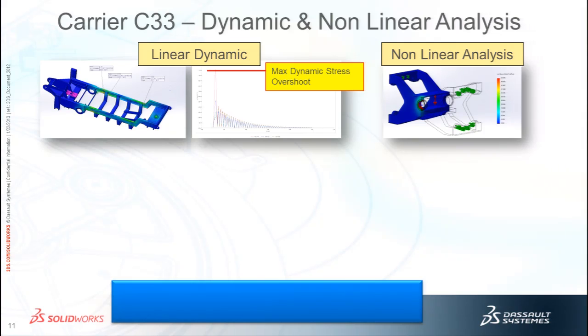Damping, yes? The damping is included in this case, and many times it's very important, always is very difficult to estimate, yes? In this case, we use, I think, 3%. And nonlinear analysis also is performed because we detected in the static analysis that we have stresses over the yield stress, so a nonlinear static analysis was performed.